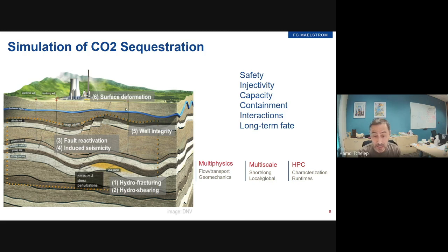Supercritical fluids tend to have densities that are more like a liquid. So the density of CO2 about 1,000 meters below the subsurface is on the order of 700 kilograms per meter cube. So it's more liquid-like, but the viscosity is a 20th of a centipoise. Think of water at the surface as 1 centipoise viscosity. CO2 in the subsurface is expected to be a 20th of that or thereabouts. So we do want to inject it in this supercritical state in order to maximize the mass we're putting away as we try to sequester the CO2 deep into the subsurface.